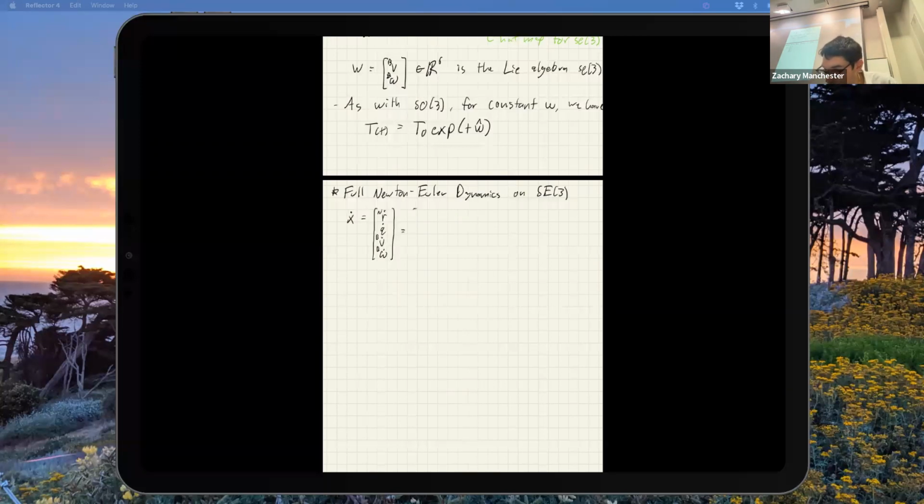So let's write that out. For the first line, remember, our state has V in the body frame, so we've got to rotate that with our quaternion to be in the inertial frame. I'm going to write it like this, just with a rotation matrix, because it's quick and easy, but you know what to do there from last time. That's pretty straightforward. The quaternion stuff we know from before, so I'll just quote that. This is our left-hand quaternion multiply, our hat matrix, and then our omega in the body frame. So we did this last time.